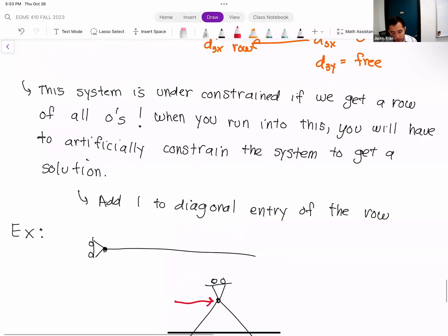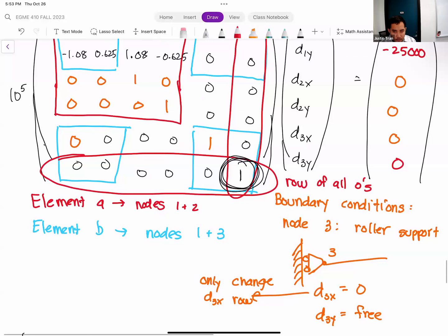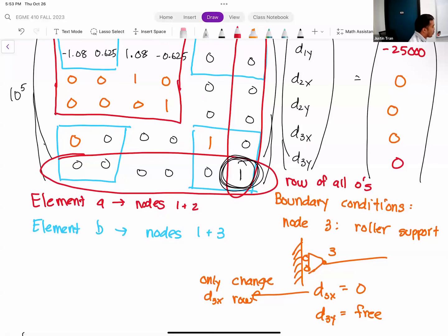Ideally, you could keep the model the way you intended. But sometimes, in order to get the simulation to work and get a solution, you have to add artificial constraints. There's a little bit of an art to it in ANSYS, to add these constraints in a way that's non-intrusive to your solution. But we'll certainly talk more about that after Thanksgiving.